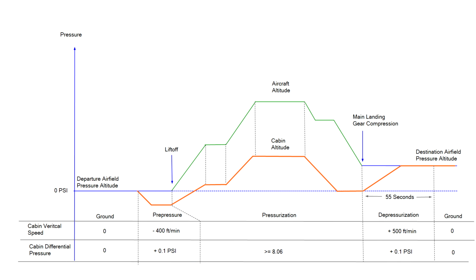Alright, let's quickly have a look at the cabin pressure chart again. And during the descent, the FMGCs compute the time until touchdown. And so the cabin pressure computer continually changes the cabin altitude until the landing. And this is where the landing field elevation comes into play.